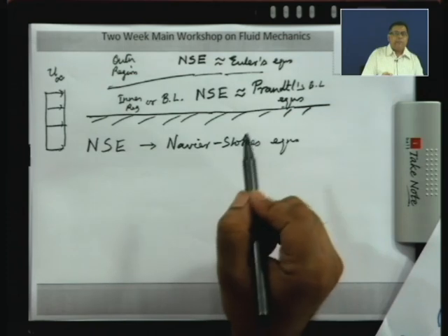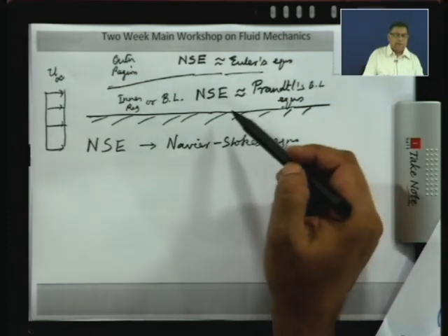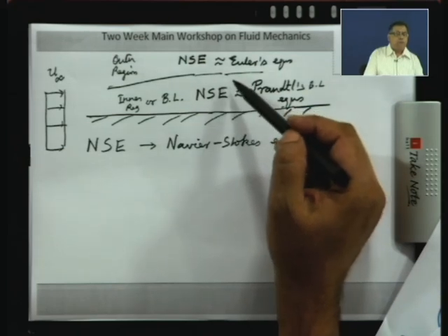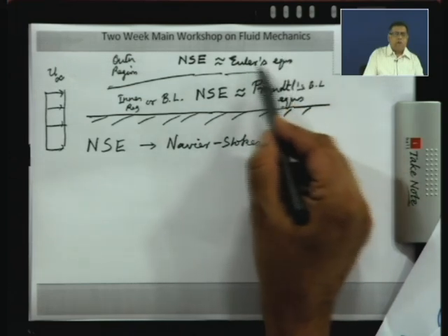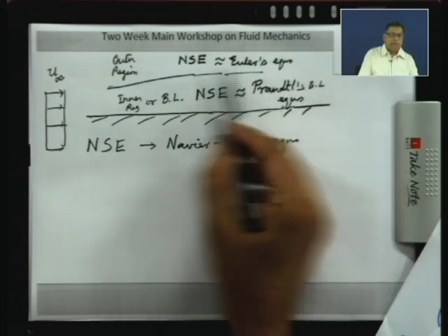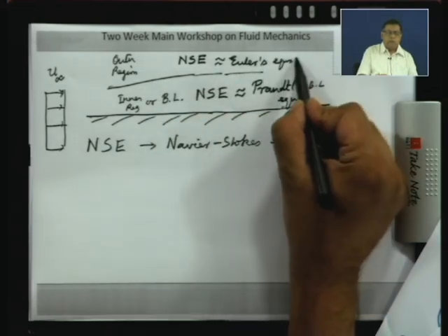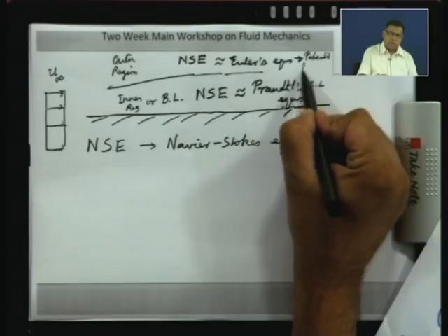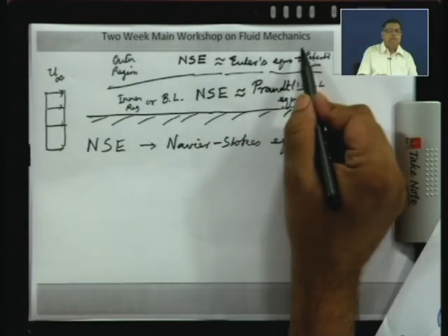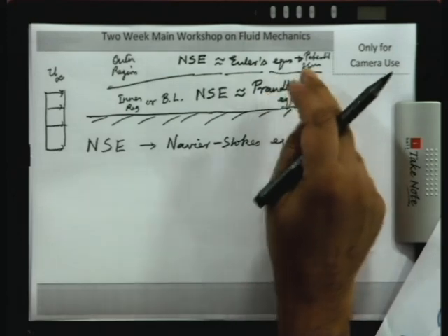So, we are trying to simplify the analysis by making approximations. We do not have one set of approximate equations which can describe the flow everywhere. So, we have two different approximations in the two regions. Now, Euler's equations are not easy to solve, but as we have seen for this particular case, when the upstream is irrotational, the flow here remains a potential flow, because vorticity remains 0, and the solution procedure for potential flow we have already discussed. So, by solving linear equations you can find the flow field in the outer region.